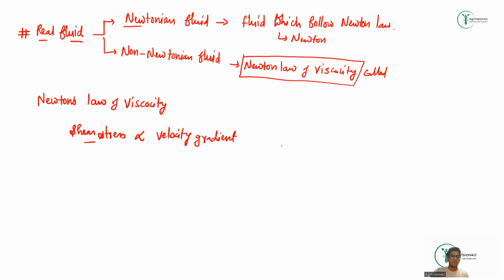Let's understand these two terms in a more elaborative manner. Suppose we have the fluid, right? And if you start applying the force here, so this layer will start moving. Apart from that, a similar profile will be created. Suppose it is having y, and suppose the velocity here is u1, here it will be u2, and this is u3. So the velocity gradient will be rate of change of velocity with respect to y, that is du divided by dy, considering it as a dy.